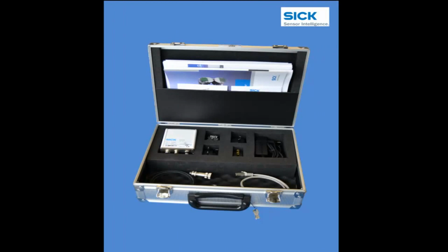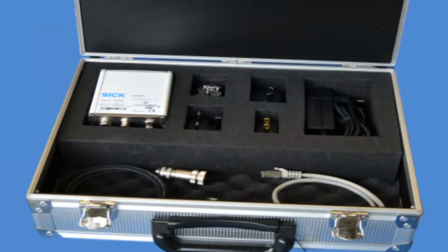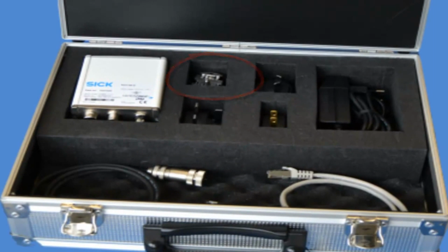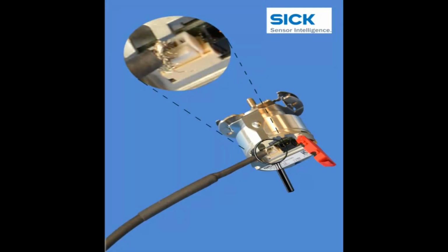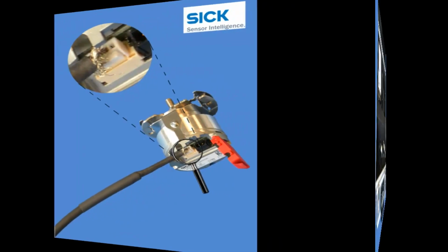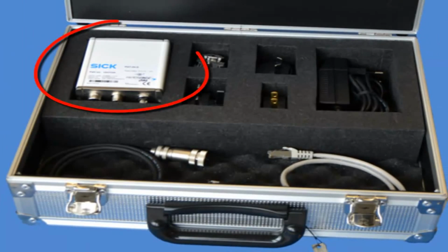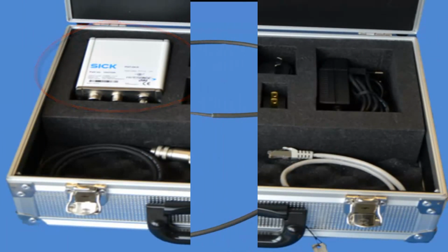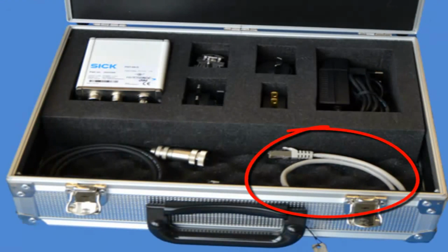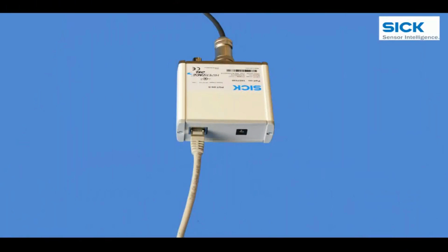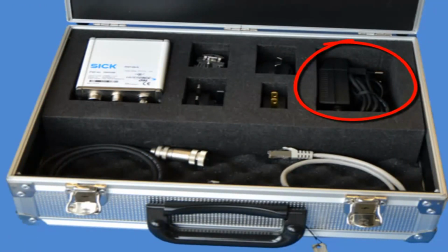In the next step, you have to prepare the programming tool as well as the encoder and their connection. Therefore, please take the encoder and add the cable with a small connector by opening the red or green cover. Now please close the cover and connect the other end of the cable to the programming tool. Then add the Ethernet cable to the programming tool and connect it to the network. Finally, please add the cable of the power supply and connect it to the power socket.